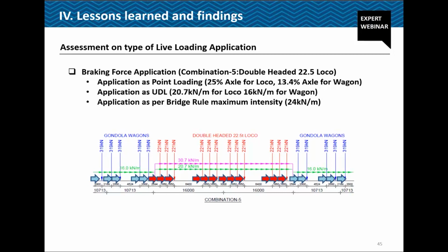But regarding the bridge rule, I understand that if we have such a short span, with just a normal track which is not CWR, and this loading is on top of this 18 meter span small bridge, we have to take the full force as transferred to the substructure. So that was the intention of this bridge rule table, not for the RSI analysis of the CWR case.